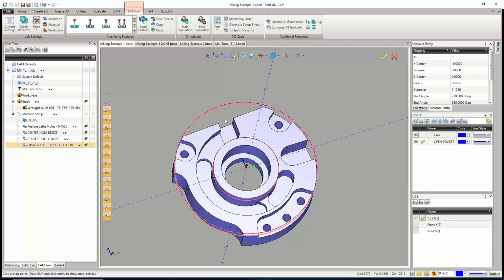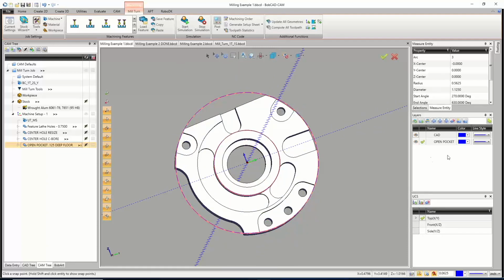Let's start by getting this whole kind of crooked pocket here down to this first level, because then we have individual pockets. So we're going to take the whole thing down first, and we'll call that our C-shaped open pocket. So add a new layer. We'll say C-shape, open pocket.